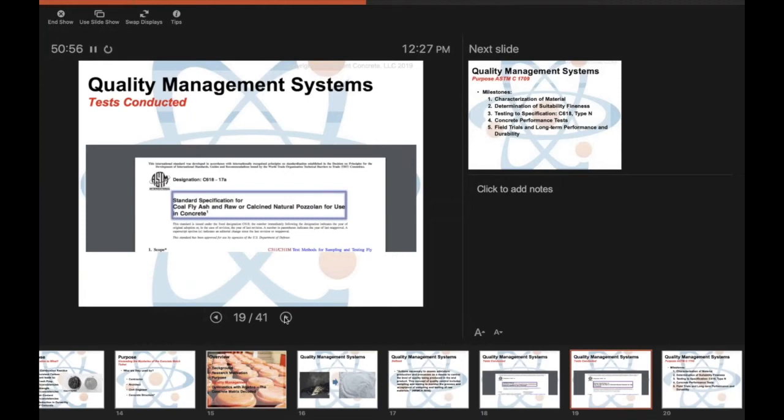And one of those, of course, is ASTM C618, and we know it very well out here in Colorado. In that ASTM, for us, we use standard specification for coal fly ash, coal combustion residue. For us is Class F ash. We do have Class C ash out here, but we don't tend to use it as much. Folks out here really rely on that Type F ash, especially to mitigate ASR. And here in Colorado, we have a pretty bad ASR problem.